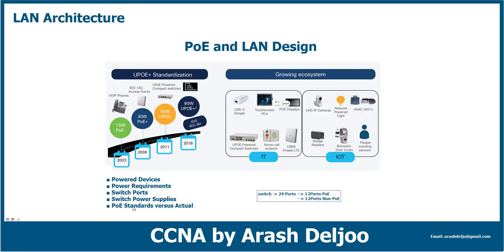And also we need to consider the PoE standards, meaning IEEE 802.3af, and also 802.3bt, okay? And after that, you can choose the correct standard, the correct switch capabilities for your device. For example, I have a device with a requirement of IEEE 802.3bt, okay? And because of that, we need to buy a switch with the capability of UPoE at least, or UPoE plus. Here you can see PoE standard versus actual.